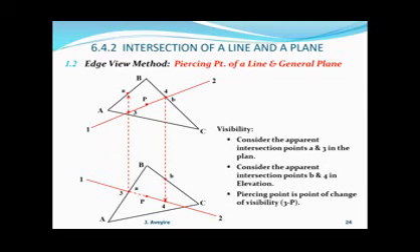We meet B first before 4. Therefore, in the front view, B is not visible because we meet B first. So if B is not visible, that means 4 is visible, right? Which means the line from that is visible to P. So the invisibility is from the point P to the other edge. Therefore, that edge will be replaced with a hidden line.